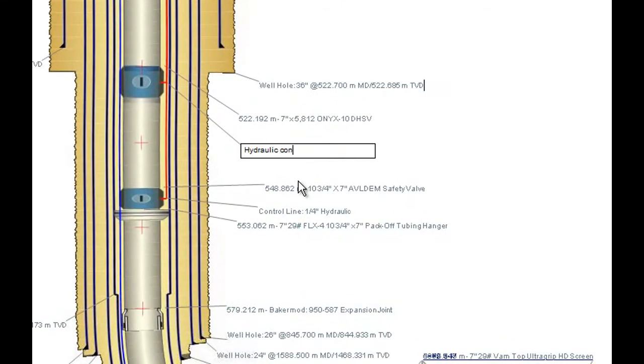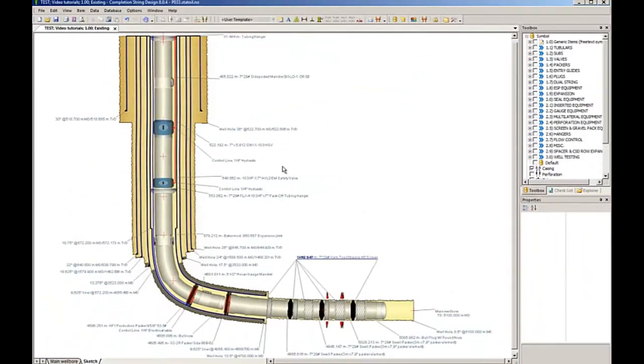As you can see, if you change the text, CSD will automatically add a star sign to the text. To get back to the original standard text, you have to enter edit mode, delete the text and press Enter. The original text is taken from the path database, and the changes you make in the sketch won't have any effect in the database.